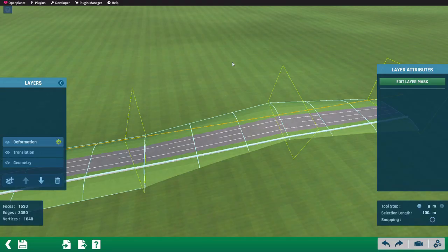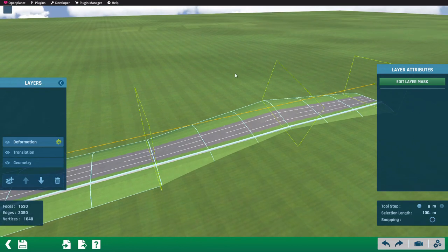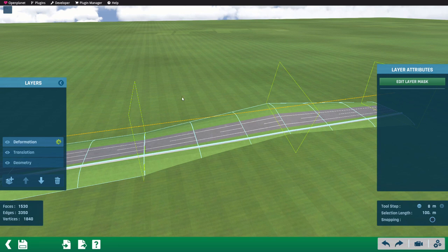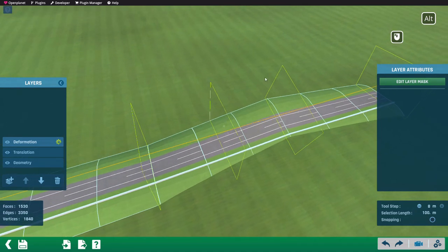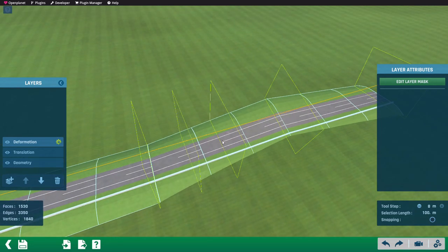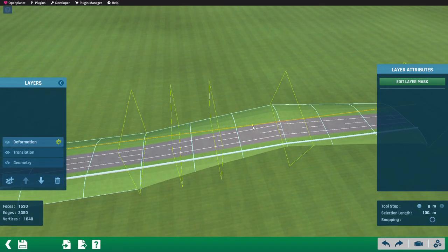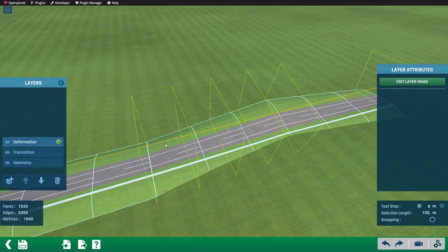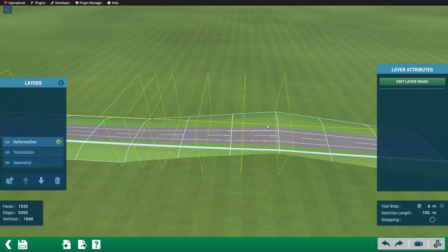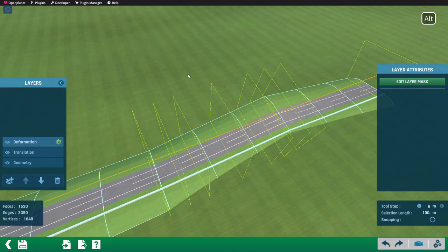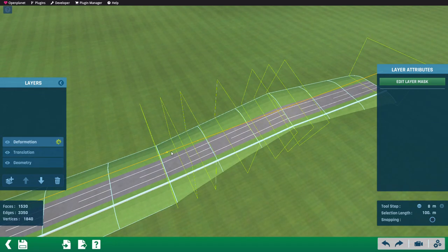Before shifting a control frame, I create the complete amount I want to have. Important are especially those close to the beginning and end of the transition. So first I insert a control frame at the middle of the transition at 50%, then to both sides again, one at 1/4 and 3/4, now again towards the side a pair at 1/8 and 7/8, another pair at 1/16 and 15/16 and a last pair at 1/32 and 31/32.